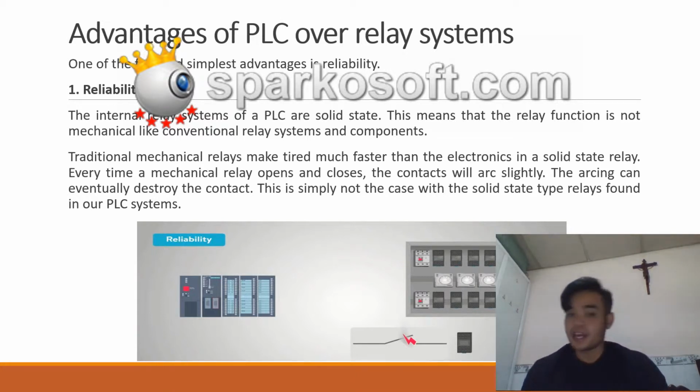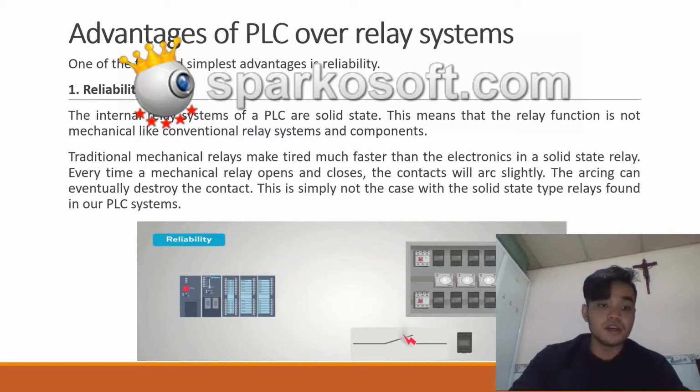Every time a mechanical relay opens and closes, the contact will arc slightly. The arcing can eventually destroy the contact. This is simply not the case with the solid state type relay in our PLC system.